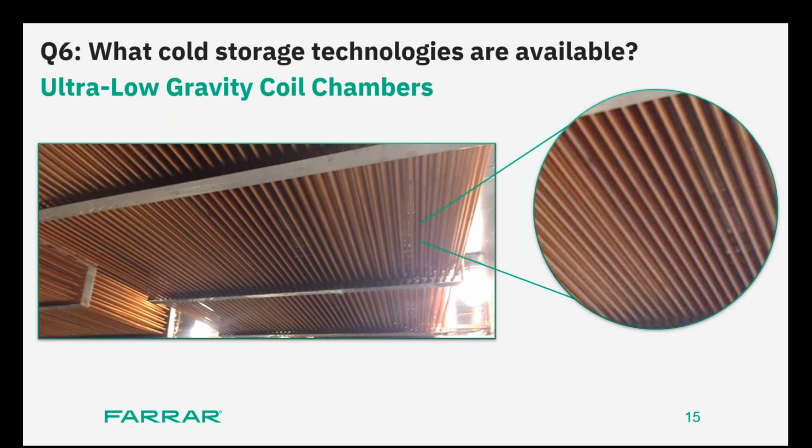Yeah, what we're looking at right here is an evaporator coil that is part of a system that's typically the cascade system for your ultra lows. So you might be minus 50 down to minus 80 degrees C. So it's a copper coil, and you're going to notice there's no fins on it and there's no blowers. It's completely gravity. So typically you might be in a hallway or in a building in production area, and you might see someone say, yes, this is where our ultra lows are located at for the walk-in solutions.